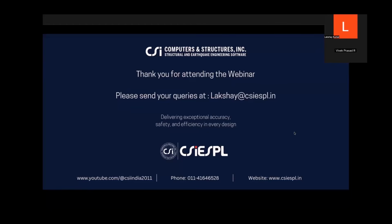How to get 0.09? In the slide I showed, it was the peak value of the lateral response spectrum we defined. I use that for the vertical. Is there a need for an initial scale factor? If we are giving a scale factor at a later stage, yes, we might need unscaled results for serviceability checks. Then you might need that.